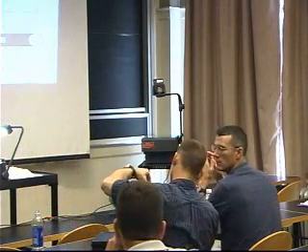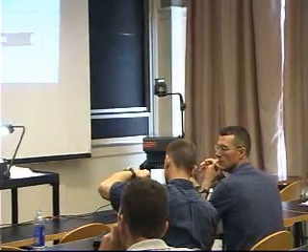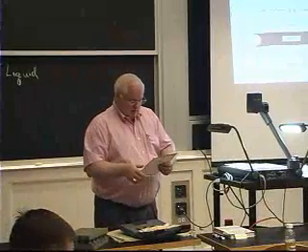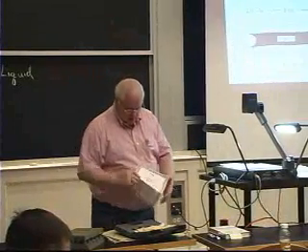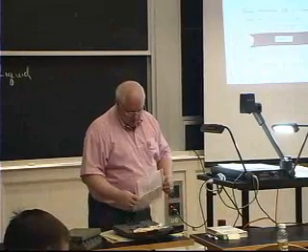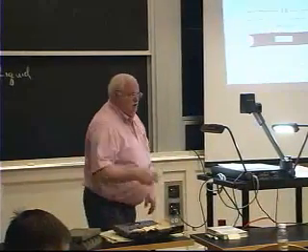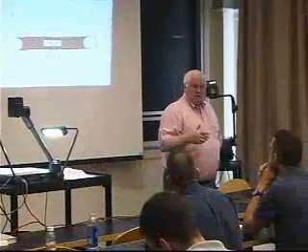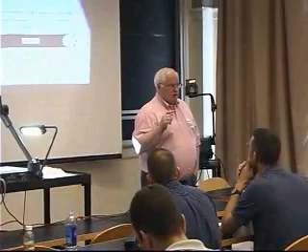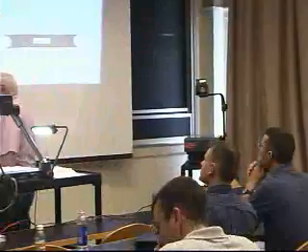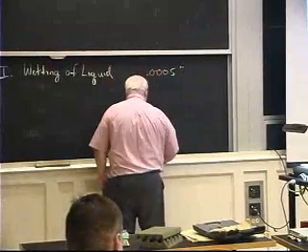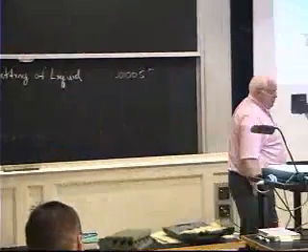If anybody wants to see the certification, traceable to the National Bureau of Standards, June 28, 1996, NIST test number, and it gives you all the calibration standards back here for these things. And so if you're trying to machine something very precisely, down within a few tenths of thousandths of an inch, because that's 50 millionths, that's quadruple-0-5 accuracy at 72 degrees Fahrenheit or whatever the temperature is.